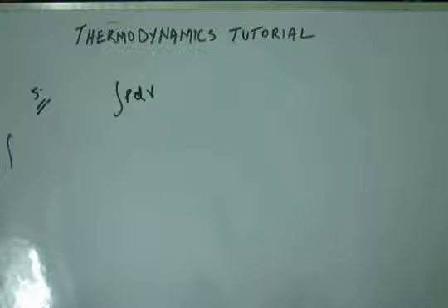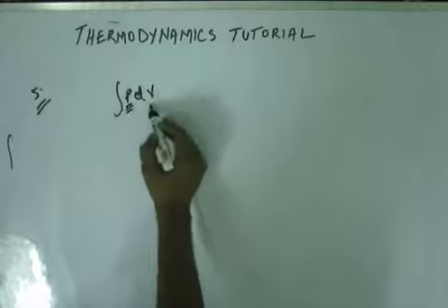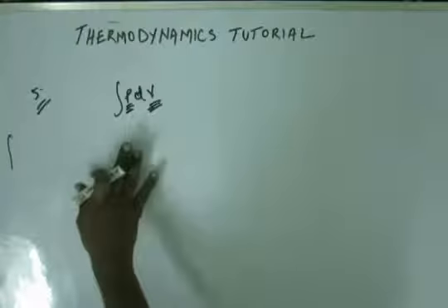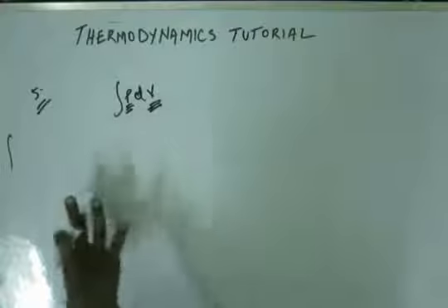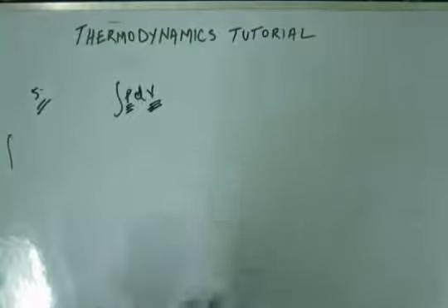So the whole concept, the whole idea and the formulas which we drew for the 5 processes, we have seen how to get the formula. Actually this is the integral. Whenever we have to find the work, we have to solve this integral. Now to solve this integral, I can't integrate pressure in terms of volume. So what I do is I somehow bring the expression of pressure in terms of volume. Then I integrate it, as we have seen in the case of the adiabatic process and isothermal process.